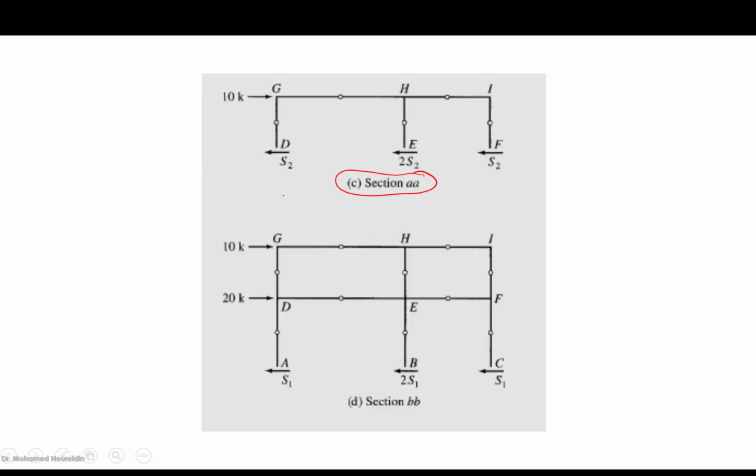Then here it is pretty simple and similar to what we have done before. First of all, the shears of the columns are going to be distributed based on our understanding. As we said here, this is 10. So definitely without thinking, this is going to be 2.5, this is going to be 5, and this is going to be 2.5.